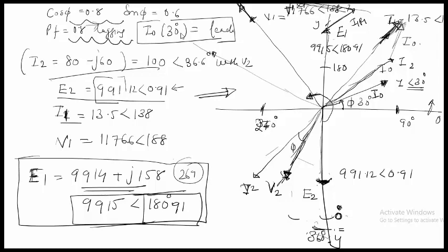And then what I found was the value of I1. Before going to I1, the value of V2 is given as 500, and if I am considering this as the value of V2, then the current I2 is making an angle phi of 36.6 degrees with V2. So I have drawn I2 here, and then after the I2 I have drawn V2 here at 36 degrees from the V2. And then the I2 could be extended as I2 dash here.